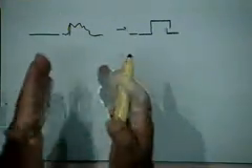Every single pulse that is coming in, which is somewhat noisy, is being converted to a clean pulse in the same position. So, the information is intact. You don't have any averaging of the signal. No, some errors will happen. I am giving an idealized answer. Obviously, you won't get a perfect answer, right? But it will be much better than what you can get through analog transmission.